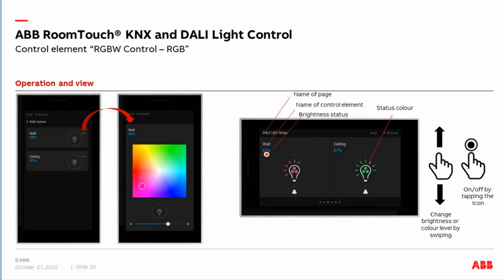And when I have enabled the parameter, I can also see the RGB brightness status as feedback. You see here, for example, these are in 10% steps: 1, 10, 20, 30, 40, 50, 60. Now this output, I have 60% brightness, between 60 and 70.